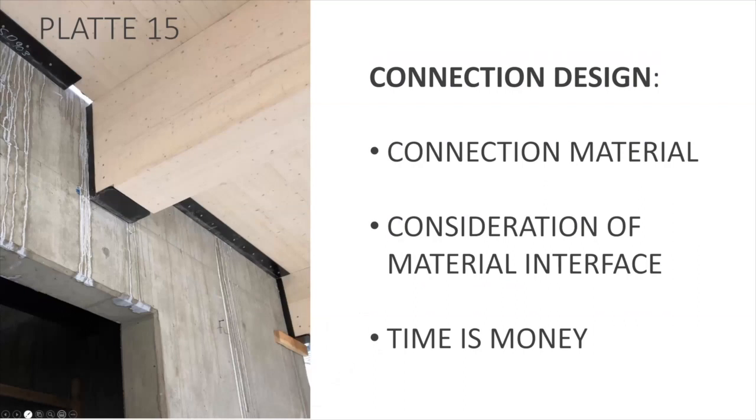Looked at the same exact condition, but at a vertical interface. This is a concrete core. This is a connection that would ultimately be exposed. We needed to be able to design that connection to accommodate our plus or minus 3/4 of an inch. Actually, I think this one can handle an inch while still looking pretty. We had some little side plates on the side to hide the gaps.